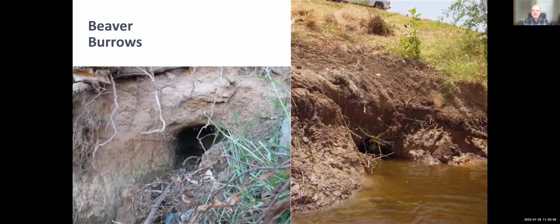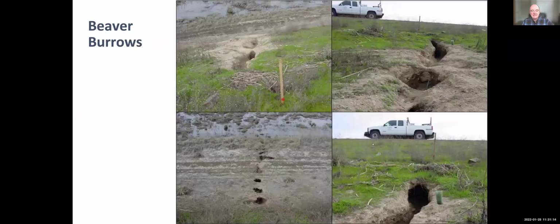And beavers can burrow. They do like to burrow, and again, they're typically starting near the water level or even slightly below it as they make their tunnels. And of course, the beaver tunnel is quite a bit larger than a muskrat tunnel. And these are examples on an embankment. And so, you get kind of concerned when you see a big hole going through your embankment.